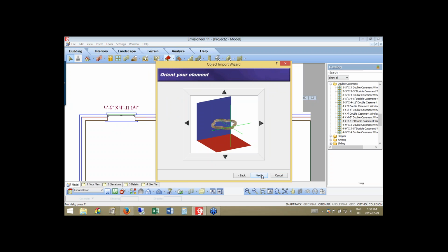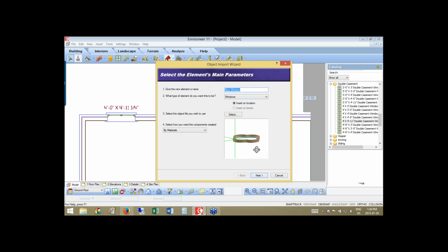When the person originally drew that window, and maybe I should step back a moment here. When I selected that window to draw, the block types that we accept and you can use in the software, you can bring in a DWG 3D block. You can use a SketchUp block, which has a file extension of SKP. You can also bring in a 3DS file, and that's a 3D Studio file. So if your window manufacturer or door manufacturer, doors can be brought in the same way, are producing their stock as DWG, SketchUp, or 3D Studio files, you can bring them directly into our software.